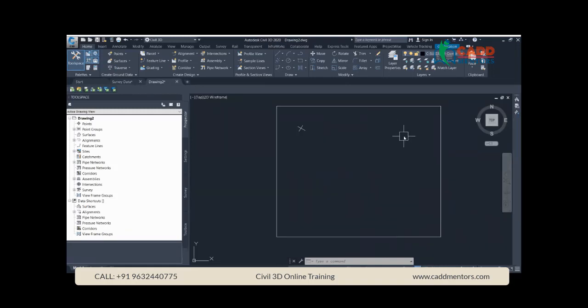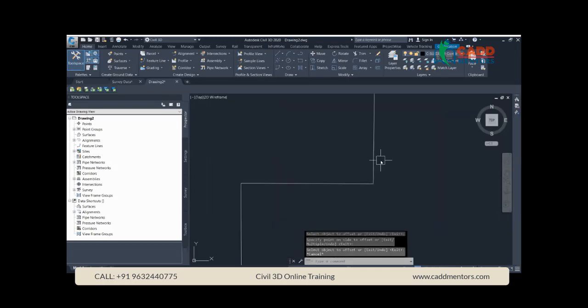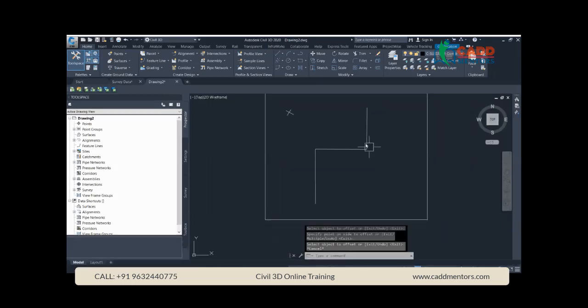When you have that much data, obviously it cannot be handled by Civil 3D. Let us assume you have a surface here, and you plan to make your alignments, something like this, and in the same way you plan to make your corridors. When I say corridor, it is just the carriageways.